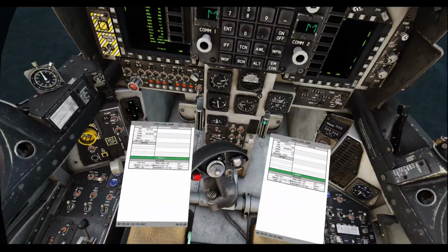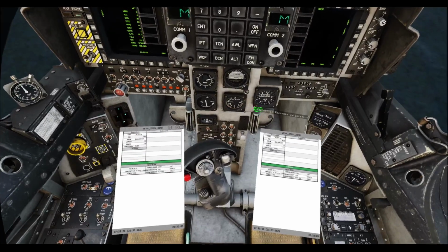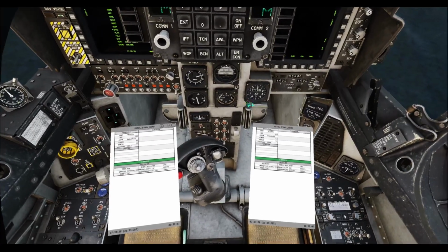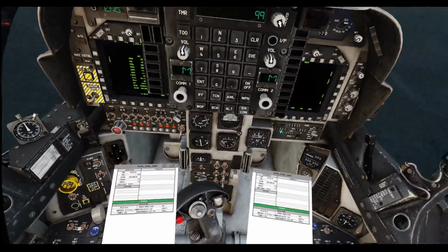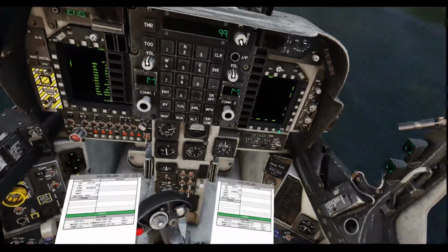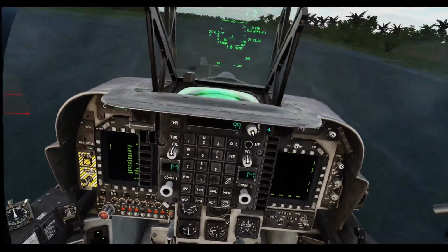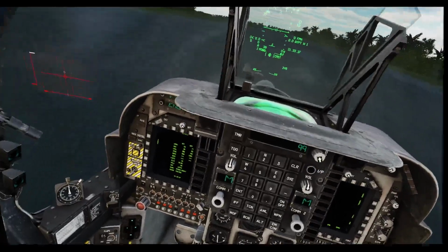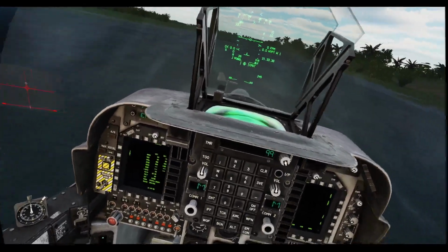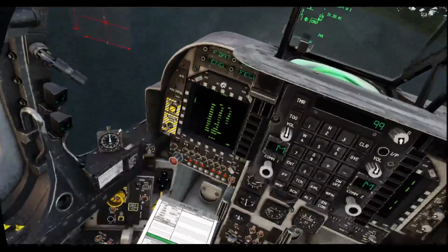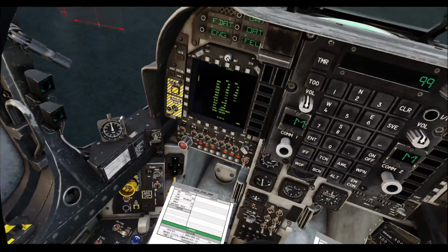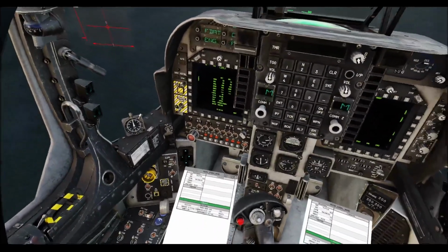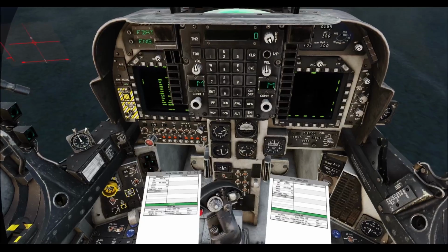Field elevation, now because it's an assessment, I'm going to zero the altimeter to get an accurate QFE, just because it makes my life easier. Again, as always, remember not to continue scrolling down after it reaches 0, otherwise when you take off the altimeter won't come alive straight away. It may come alive at a much higher altitude and give you a false reading. Okay, field elevation we are going to set to 0.